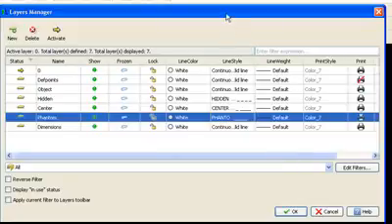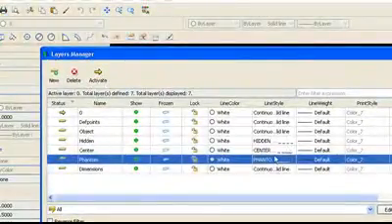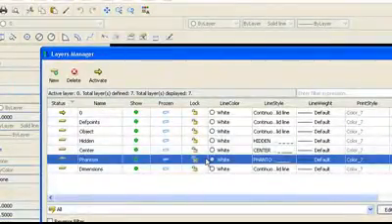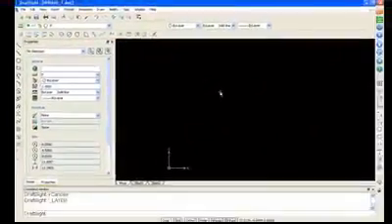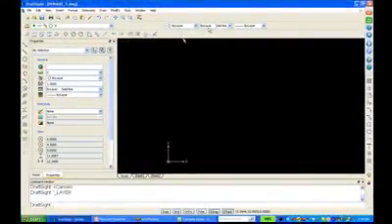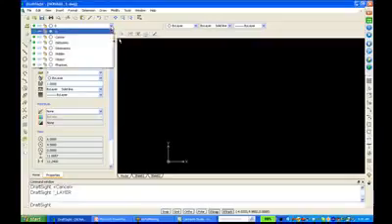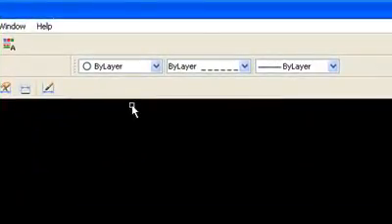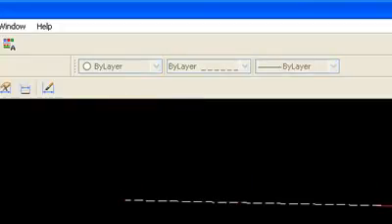It's really important that you map your line styles and your layers together to make your drawing a little bit more neat or clean. When you create your geometry, what you're going to want to do is make sure that your line style is set by layer, and then if I just change a layer, my line style will change. So now if I draw a line on that layer, it'll become dotted or hidden.